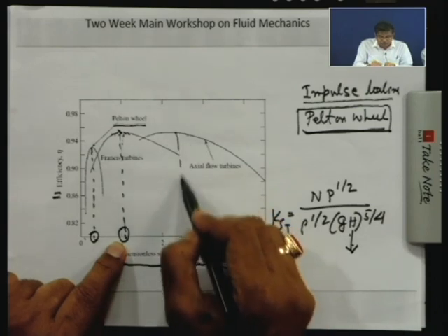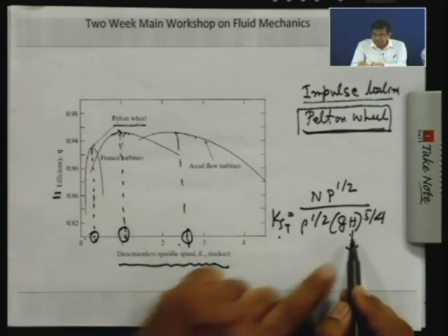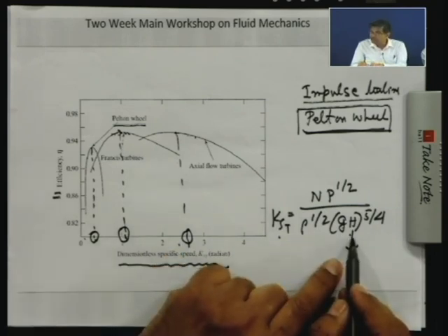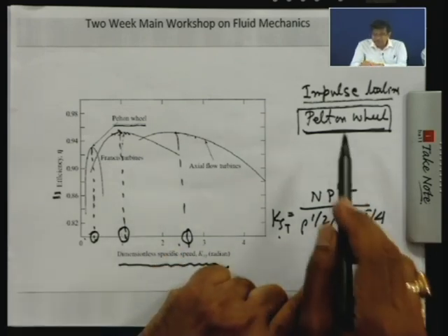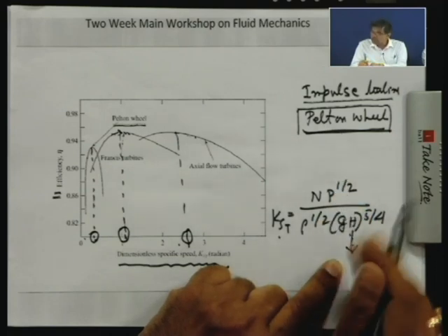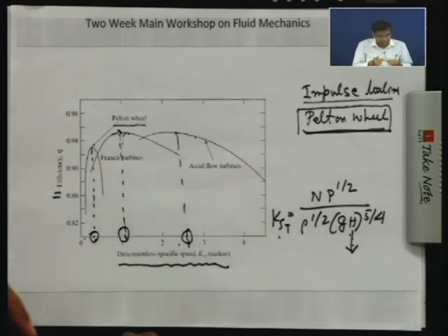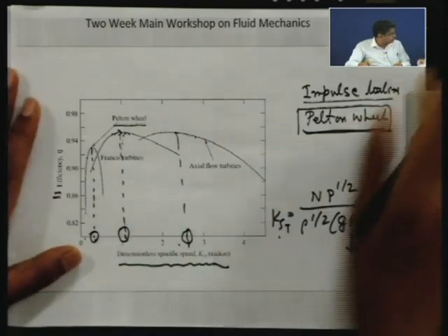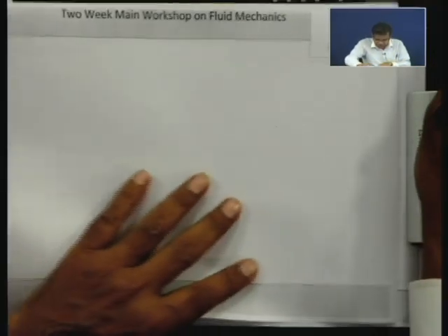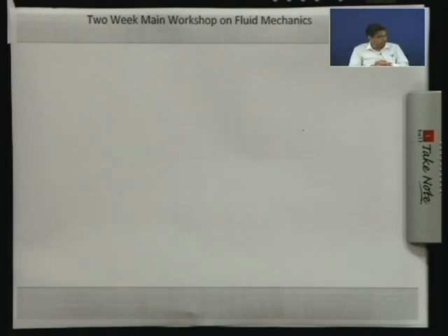Axial flow turbine works at a higher efficiency when the specific speed is very high, that means at a lower head. So in sequence, the impulse and reaction turbines, radial and axial flow, are used as the available head varies. Okay. I think after this, this chapter is closed, and about hydraulic turbines I do not want to add anything because we cannot start anything as we have not gone through impulse turbine.